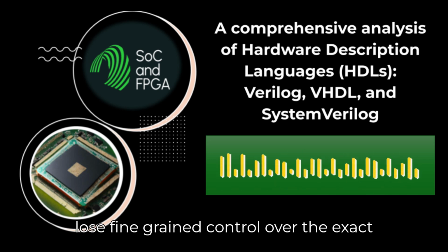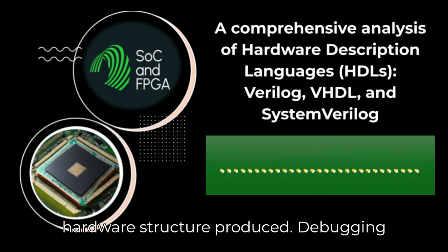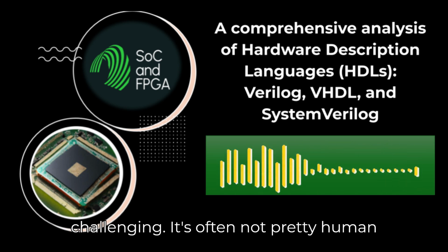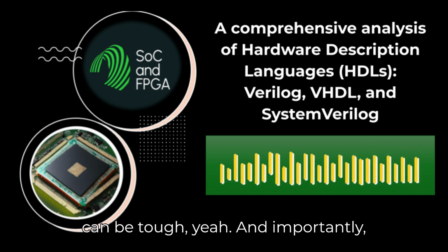You often lose fine-grained control over the exact hardware structure produced. Debugging the generated RTL can be quite challenging. It's often not pretty, human-readable code. So you might not understand the hardware it creates. It can be tough, yeah.